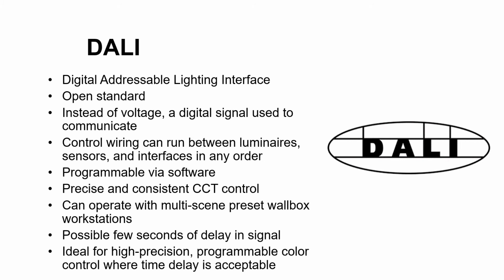DALI stands for the Digital Addressable Lighting Interface. Also originally designed to control fluorescent dimming ballasts, the controller sends a signal to the LED driver that ranges between 0 and 255 in integers, which an algorithm then translates into light output. While this can be precise and results in consistent color control, note that DALI drivers may be designed for different dimming curves, resulting in different relationships between input signals and light output.